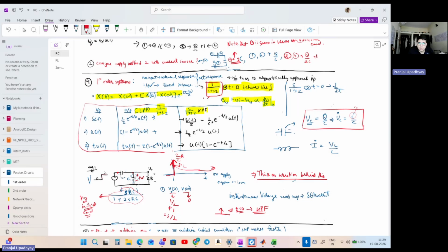The main idea is this only, that if there is a sudden change of voltage happening across the plates of a capacitor, then some impulse current will be flowing. But here, since this impulse current is flowing entirely to the resistor, which determines the output, that's why we are seeing an impulse. But okay, let us try to change the scenario a bit.